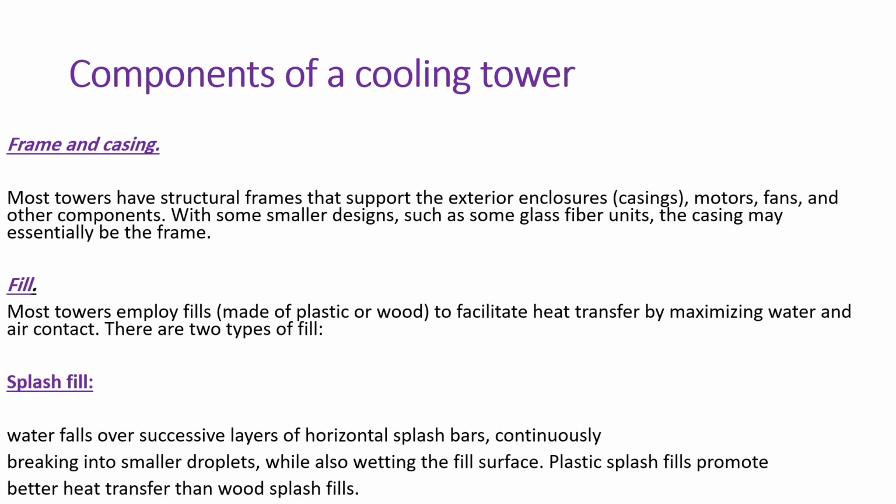In splash fill, water breaks into droplets while falling over bars. Water falls over successive layers of horizontal splash bars, continuously breaking into smaller droplets while also wetting the fill surface.